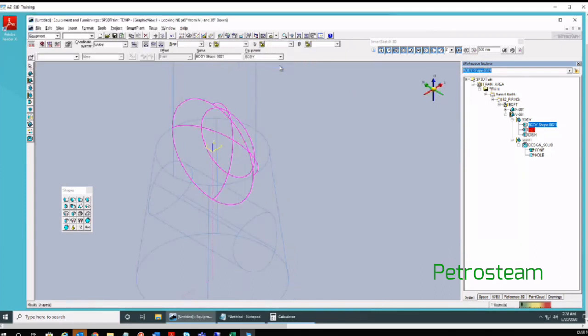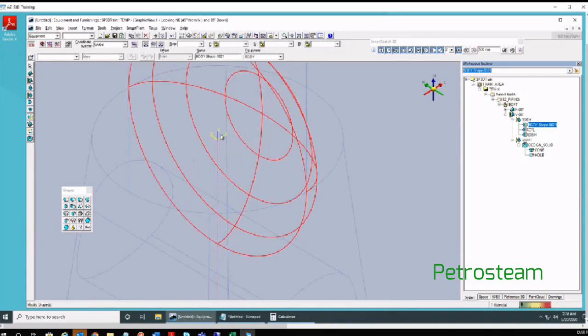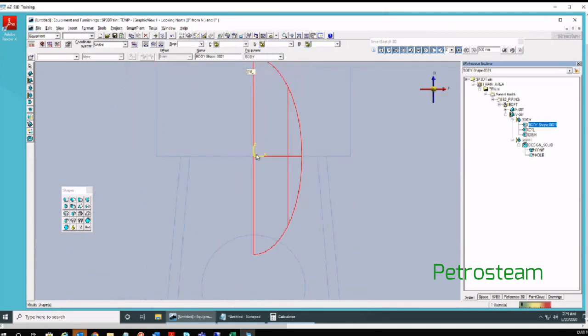In the isometric view, I will activate the Y axis, which is the north-south axis. Using the up arrow, I have activated the Y axis now. I will come back to front view to rotate. Once the Y axis is active, I can use the left or right arrow. If I use the right arrow, I know that it will rotate in this direction.